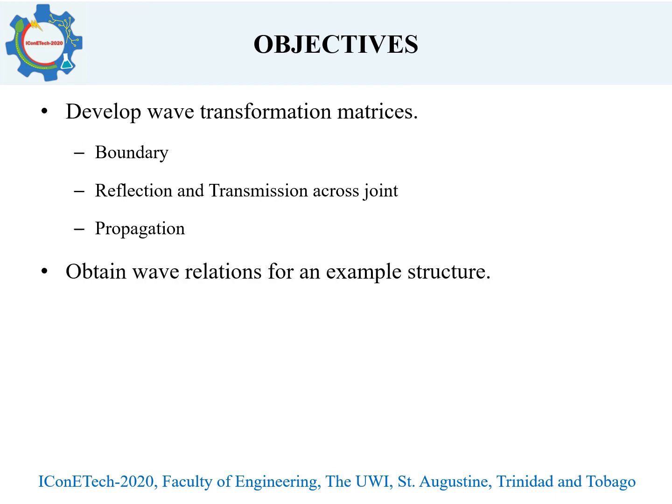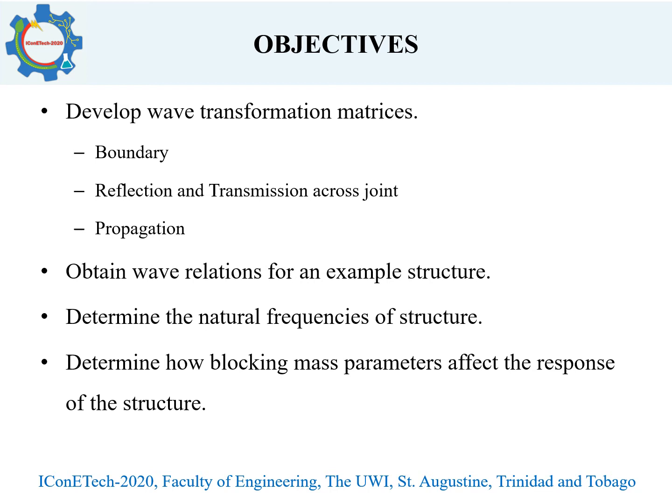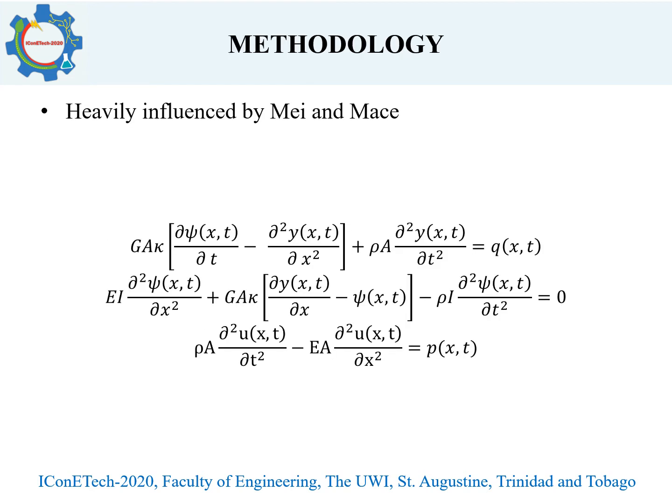For wave analysis, you must also obtain the wave relations. These are equations showing the relationship between various wave components of the structure. These wave relations can then be combined to make a global matrix, which can then be used to obtain the response of the structure, in this case, the natural frequencies. And finally, I will be manipulating the blocking mass parameters to see how it affects the response of the structure. The overall methodology used in the study is heavily based off of May and Mace's work shown in the references.